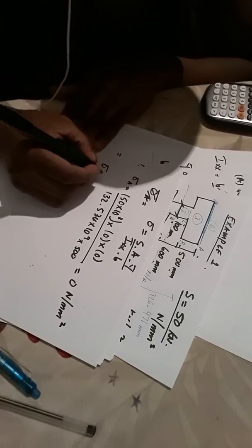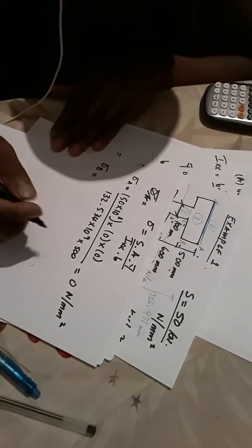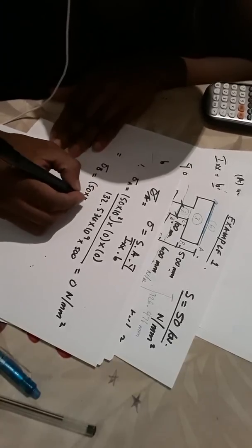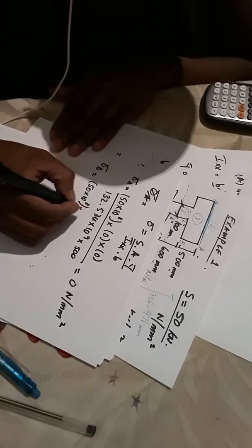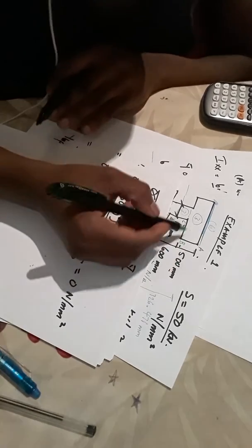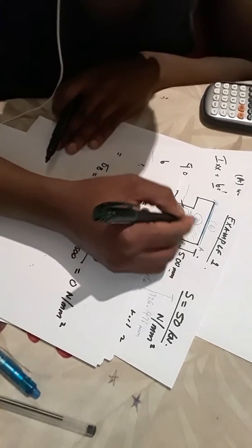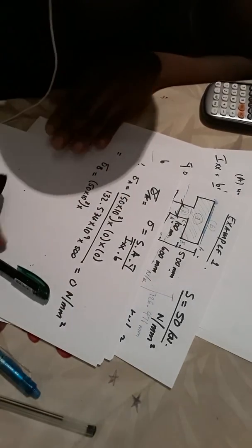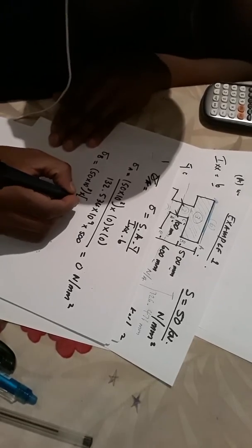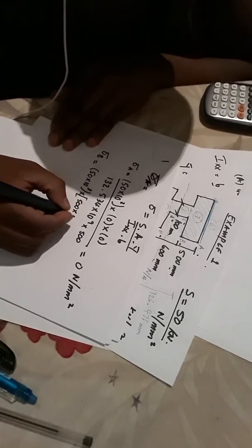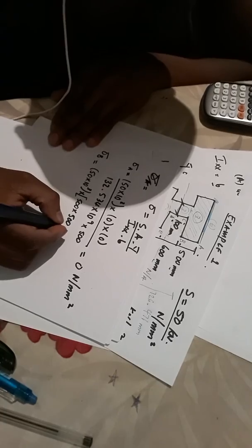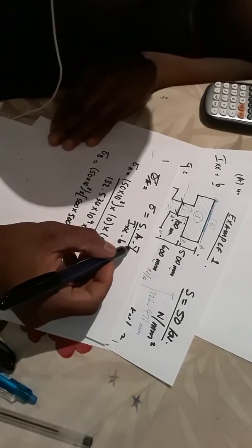And then we calculate shear stress at B. So shear stress at B, again, it will be 50 times 10 to the power 3 times the area above point in question. So we are at B, so we have the area above point in question. So the area above point in question will be 500 by 500 times y dash bar.